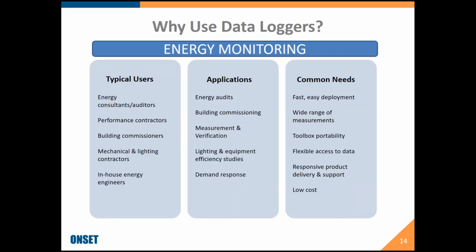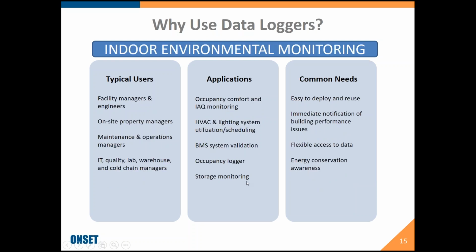Why use the data loggers? Well, for energy monitoring, there's a lot of uses. Building commissioners use them, performance contractors use them, in-house energy engineers use them, and they use them for monitoring lighting, just for measurement and verification, for energy audits. A common need is that it's a toolbox portability. In other words, you can bring it with you and set it up and leave it. Relatively low cost and fast deployment. A lot of times you need to be able to set that up rather quickly.